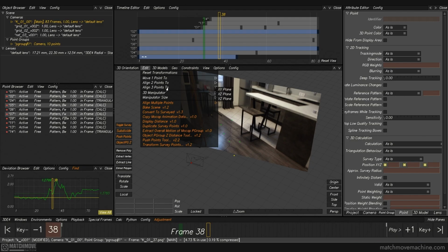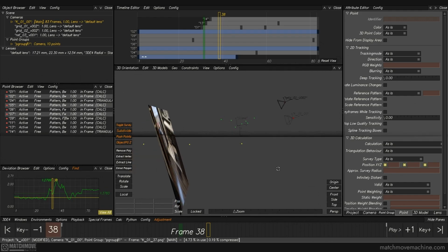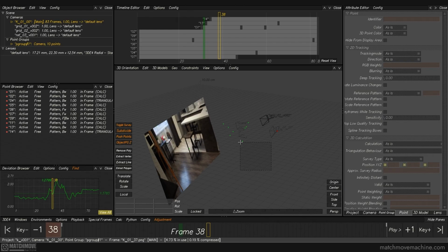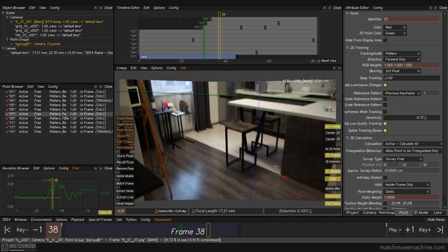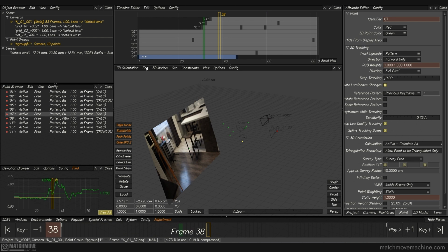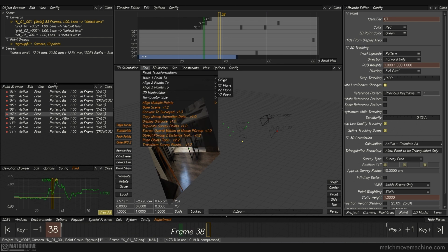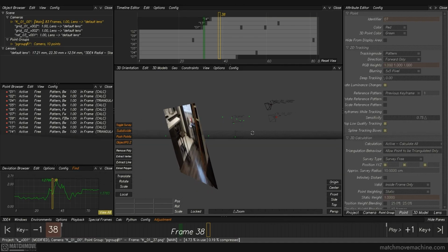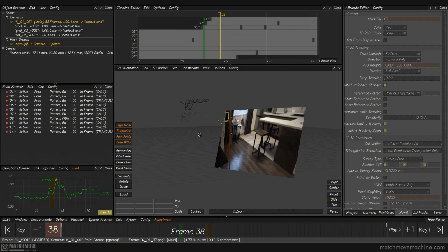Right now we selected 3 points and placed them on a single plane. Let's take a look. They're on the same plane now, but not at 0 on Y. To move them to 0, we do this. We select the point we want to place at 0. I'll take this one. And through Edit, move 1.2. Origin, we move it to the origin. And this is what we get.